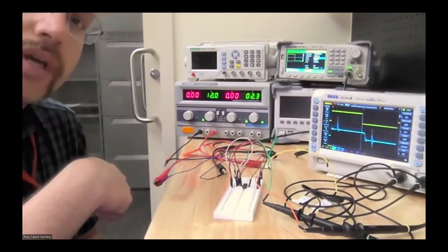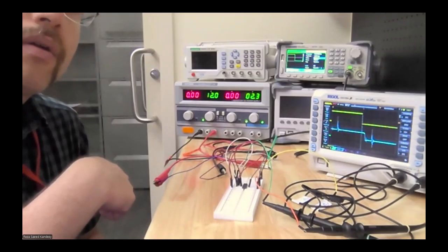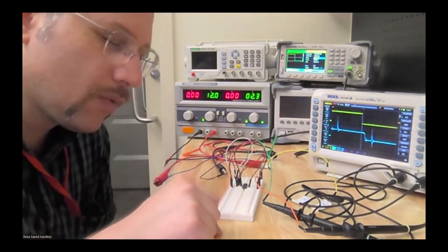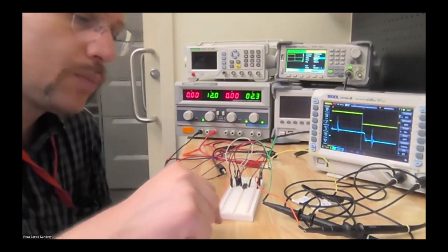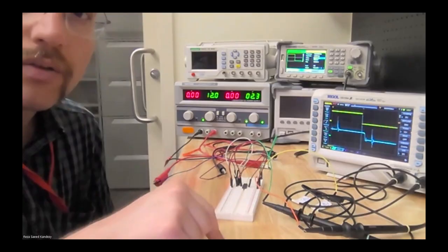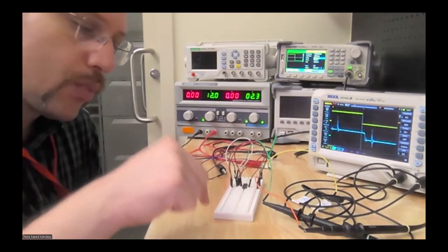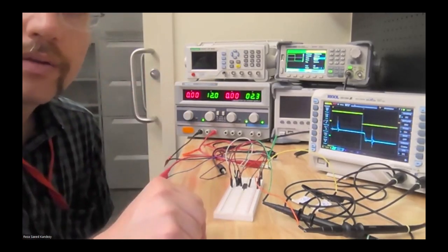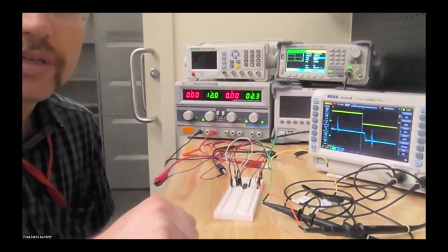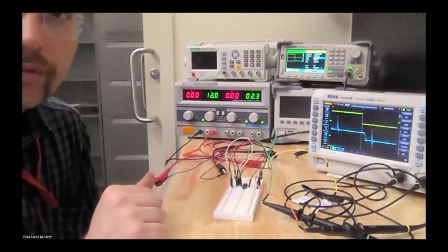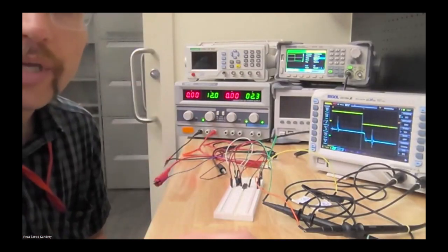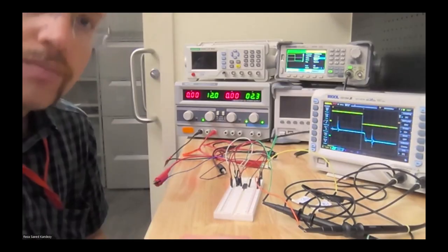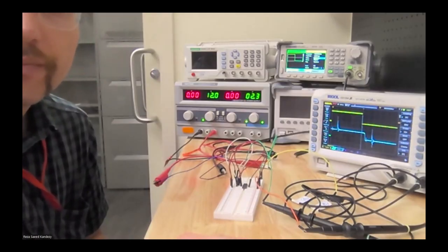Before, it was lower. Right? No, it was higher, because 300 millivolts over 2 microseconds would be 0.15. So the rising edge was 0.15 volt per microsecond, and the falling edge is 0.1 volt per microsecond. So it's slightly different, but close to each other. This is how you can measure the slew rate of your op amp. Let's move on to the next concept.